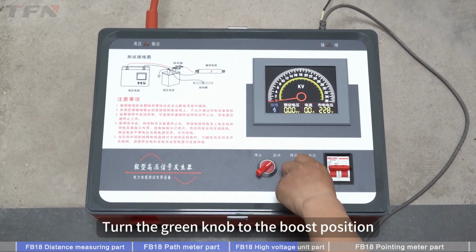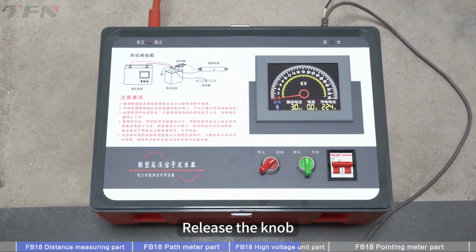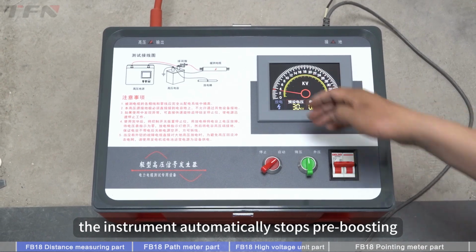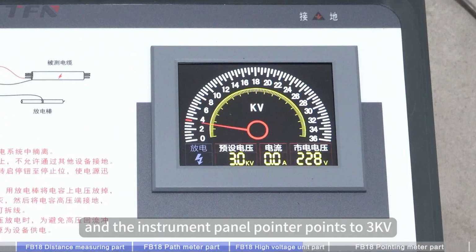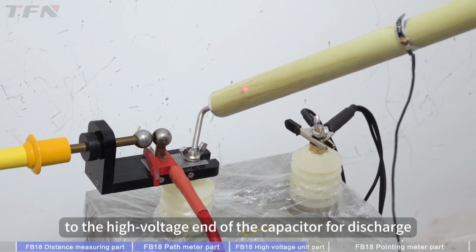Turn the green knob to the boost position to increase the voltage to 3 kV. Release the knob. The instrument automatically stops pre-boosting and the instrument panel pointer points to 3 kV. Touch the front end of the discharge rod to the high voltage end of the capacitor for discharge.